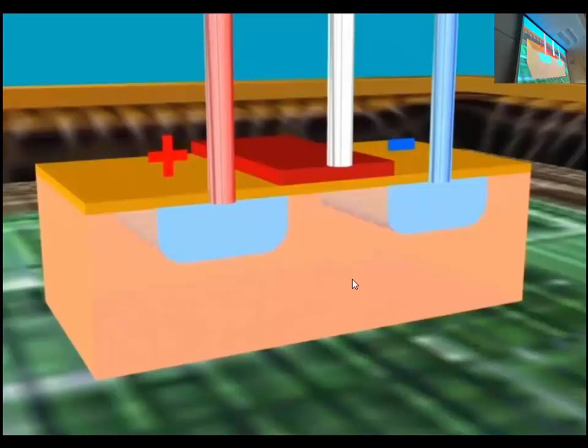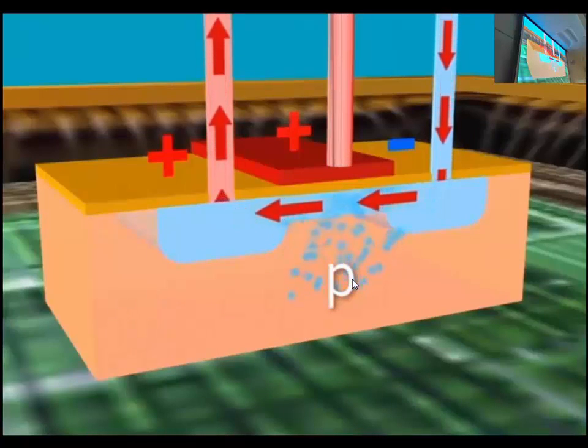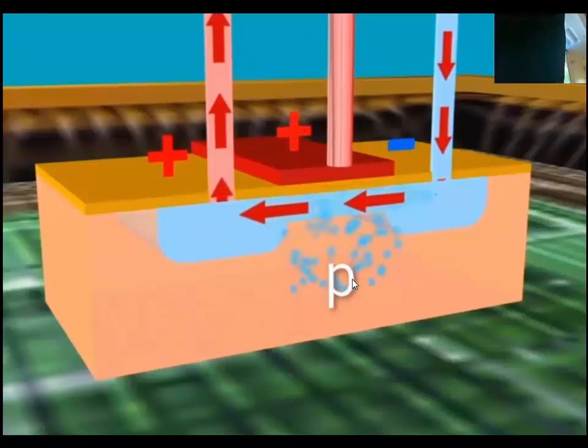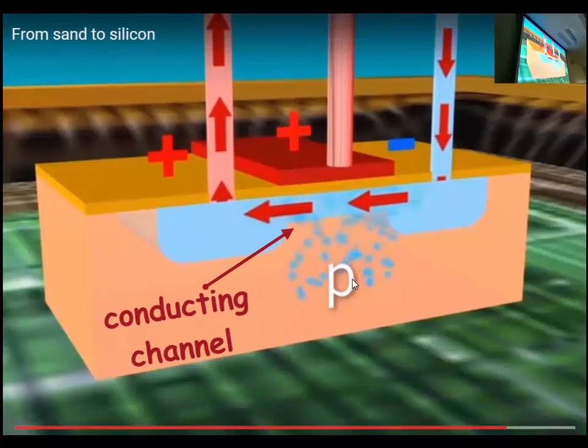If we apply an electrical charge only to the two outer connections, electricity is unable to flow. The transistor is blocked. Things are different when an additional charge is attached to the middle connection. The electrons from the P layer now wander toward the middle connection and accumulate at the border area between the silicon crystal and the insulation gate oxide.